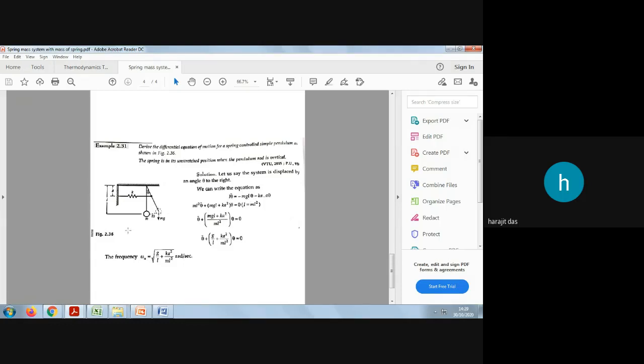Its direction is leftward, meaning the clockwise moments are taken as negative, because the theta direction is taken as positive. The displaced theta direction is from the left hand side to the right hand side, which is why it is taken as positive, and this moment is in the opposite direction of theta, so it is taken as negative, minus this spring force. The spring force will always act linearly, and translationally. So this spring force will not act in an angular way.